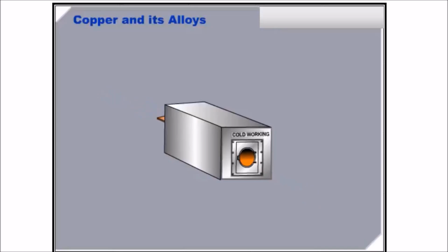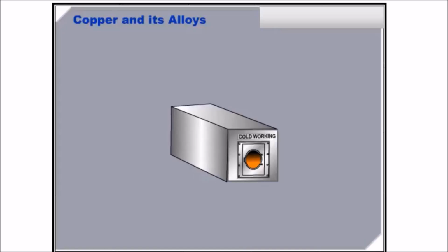There is a series of copper alloys that are strengthened by aging, a treatment similar to the precipitation hardening used on the PH stainless steels. When welding on these alloys, a post-weld heat treatment is usually specified to restore the original mechanical properties.